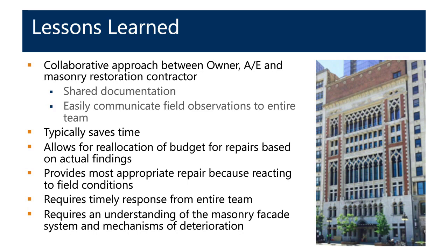It allows reacting to field conditions quickly, with the AE being out on the building a lot. We find in our work that construction period services are really helpful for an AE. Everybody can guess how it's designed and look at drawings, but things are different in the field. Nothing's ever installed exactly the way it is shown or anticipated. There's always something that pops up, and you may have to move something, as easy as moving an anchor from the side to the top, or sometimes redesign something in the field quickly, working with the contractor to get the project going and on time.